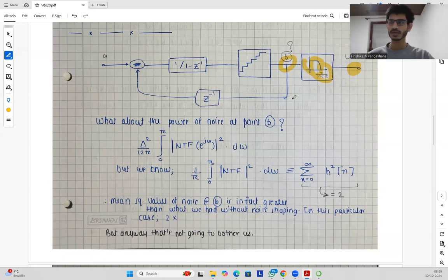Even though the noise is getting complicated, we are pushing that noise away to higher frequencies. So we get better resolution, because even if the noise is increasing, it is not going to bother us, since after the quantization we do the decimation filtering, or smoothing out.